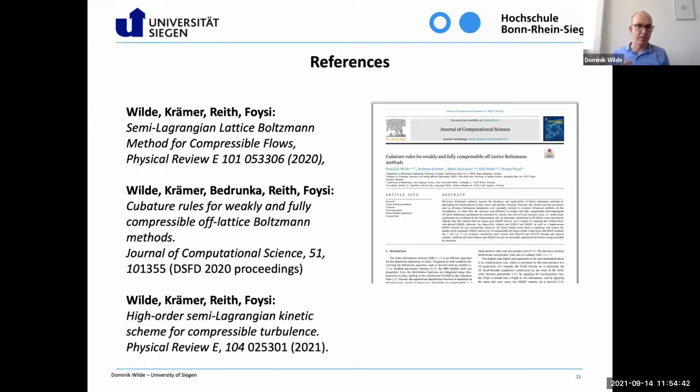Normally you define your CFL number in terms of your largest discrete velocity in your stencil, right? And I would say that you can reach CFL numbers for the Lagrangian vortex, for example, up to 10 or 20.